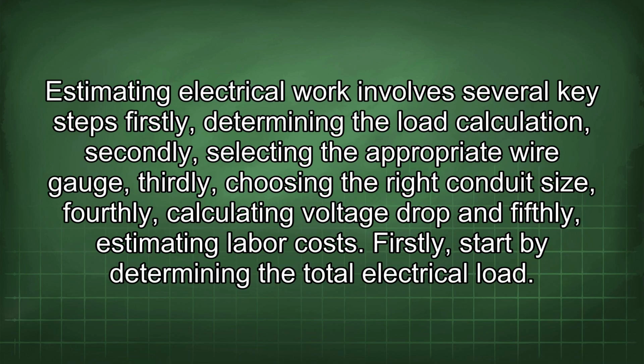Estimating electrical work involves several key steps. Firstly, determining the load calculation. Secondly, selecting the appropriate wire gauge. Thirdly, choosing the right conduit size. Fourthly, calculating voltage drop. And fifthly, estimating labor costs.